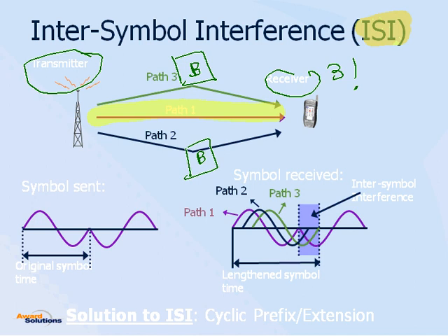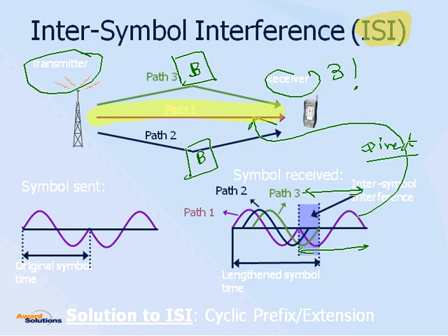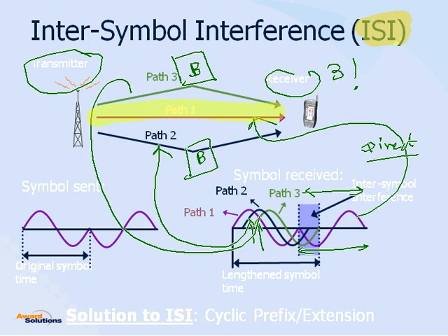Well, when we are looking at our modulation symbol period, this would be the direct path coming to us in a straight line fashion. But when we are looking at our current symbol, the previous symbol has those delayed copies, so they will be arriving on those reflected paths.